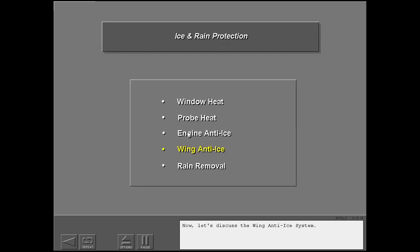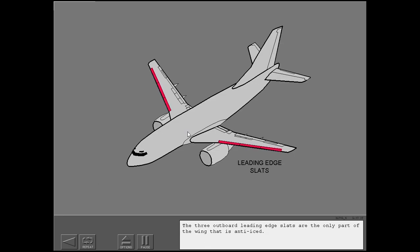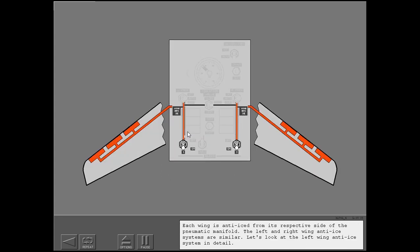Now let's discuss the wing anti-ice system. The switch and lights for the wing anti-ice system are located on the overhead panel. The three outboard leading edge slats are the only part of the wing that is anti-iced. Each wing is anti-iced from its respective side of the pneumatic manifold. The left and right wing anti-ice systems are similar.